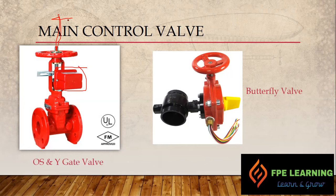Water has a force, suppose 150 psi coming, and suddenly you are closing the line. Where should that pressure surge go, right? It must go somewhere, let's say at the fittings, corners, elbows and tees. It might leak or it might break. It might damage the hangers or it might damage the integrity of the fire protection system. We have to be careful that our system's control valve cannot be closed within 5 seconds, to avoid water hammer. Now the next option we have is the butterfly valve, right?